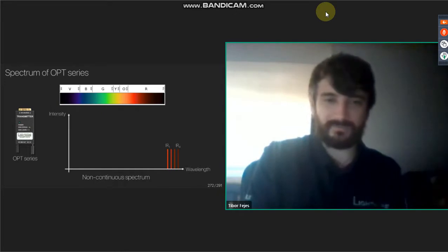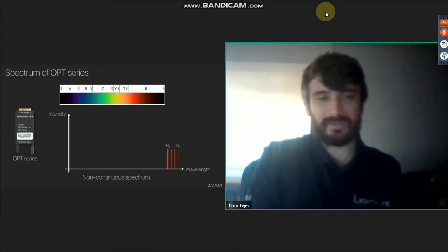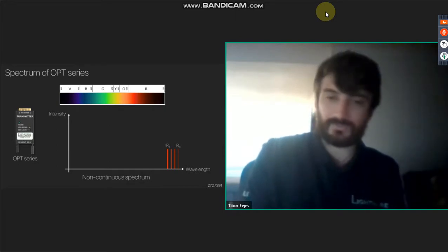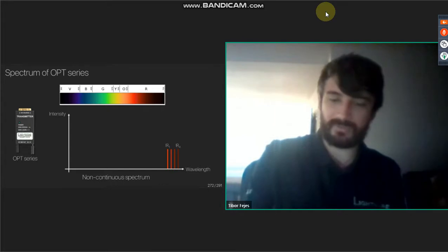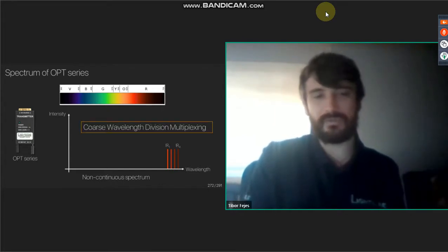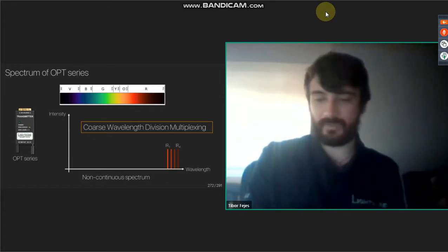And here with this OBT device, you can see we've got 4 different channels. In this specific device, these channels effectively act as the 4 TMDS channels. So in this way, we can have the full TMDS signals sent down one fiber. You can multiplex these wavelengths together using a technology called coarse wavelength division multiplexing.